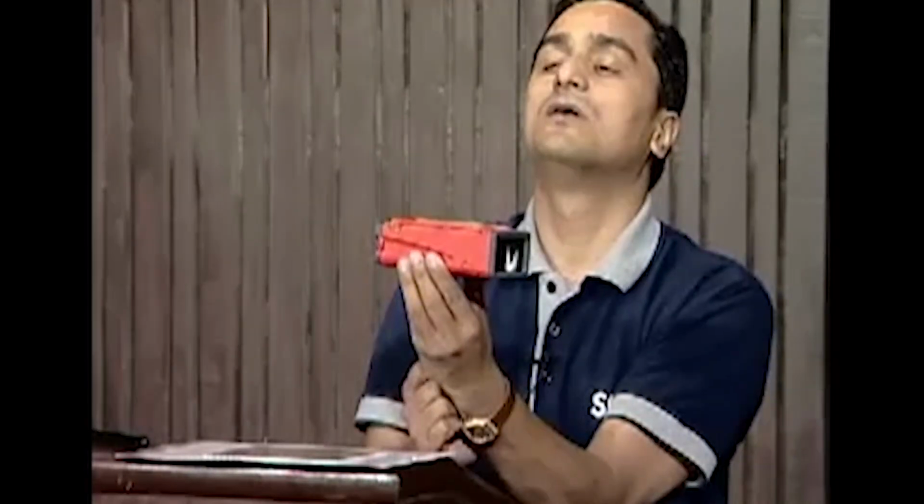What I do, I measure the distance about this face of the instrument. So my distances physically in the ground are being measured from here, while actually the laser is being fired from there. Now this distance is the instrument correction, because we need to know about it. We need to add this particular one to the measured distances. That is how I will know about my distances.